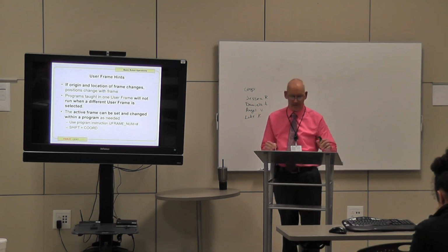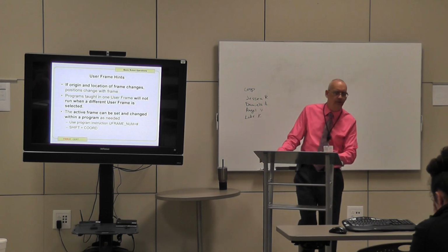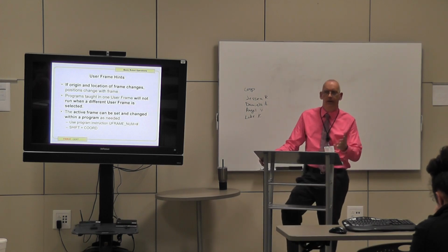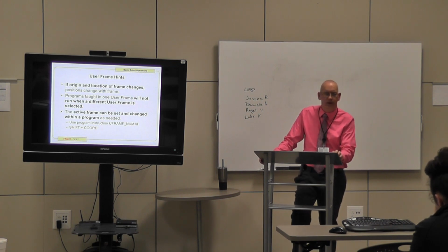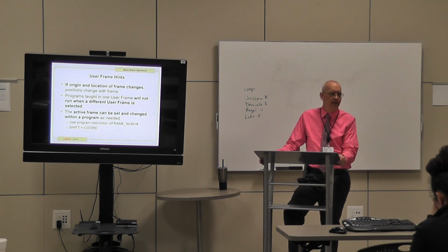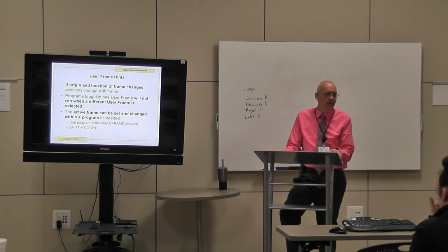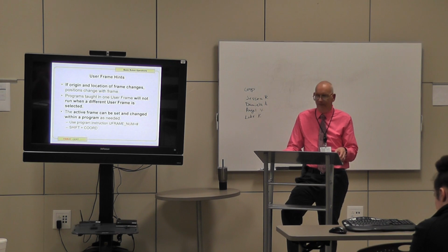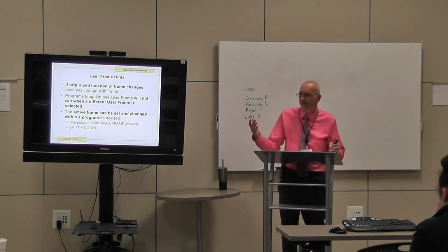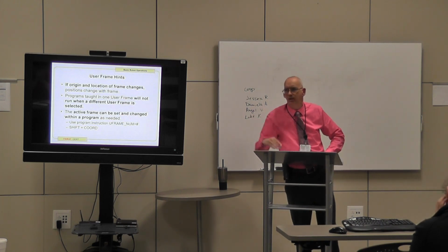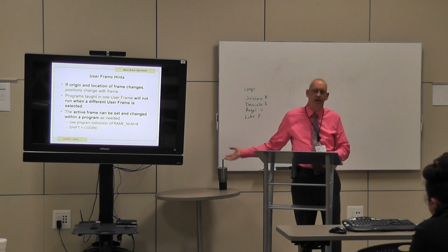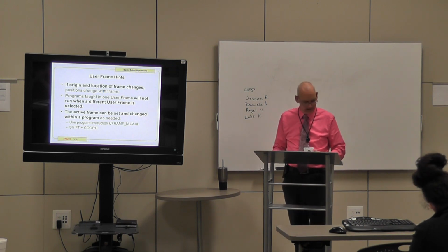Okay? If you don't assign a user frame, then you're going to end up being in which one? Anybody tell me? We've talked about it. What's the default? World. The world frame is your default. So if I don't go and do what I need to assign my user frame, then it's automatically going to be the default frame of the world. All right.